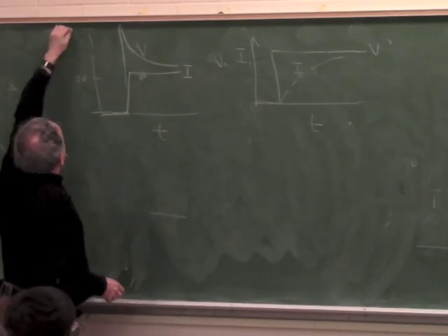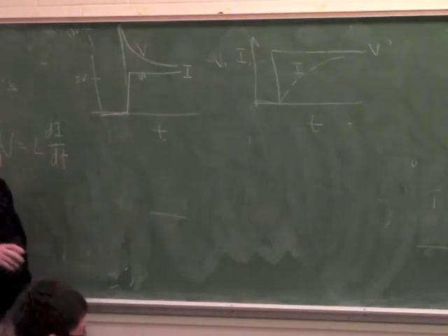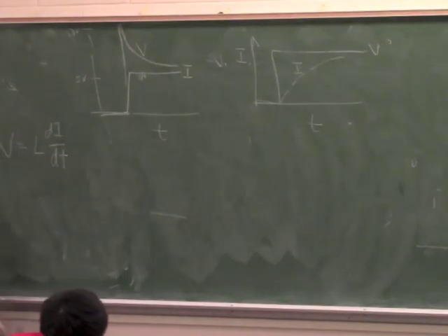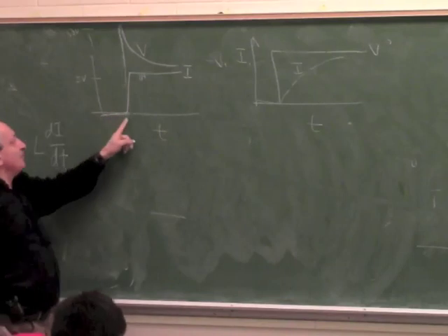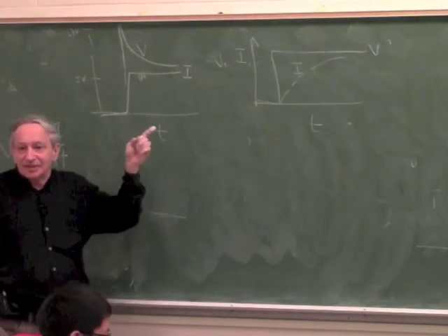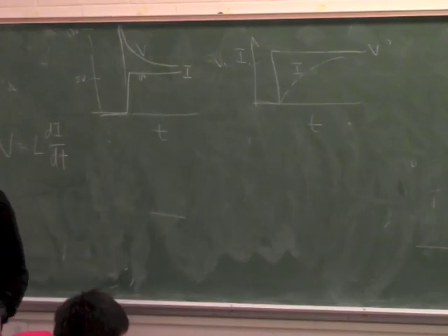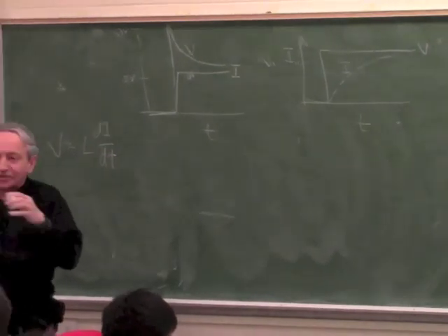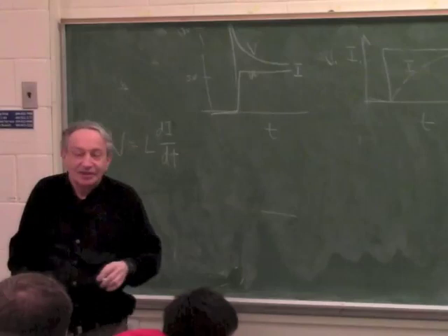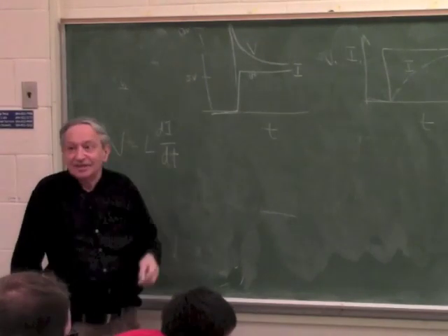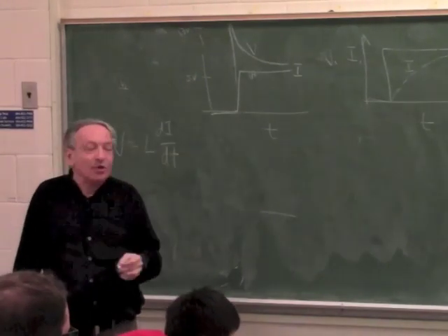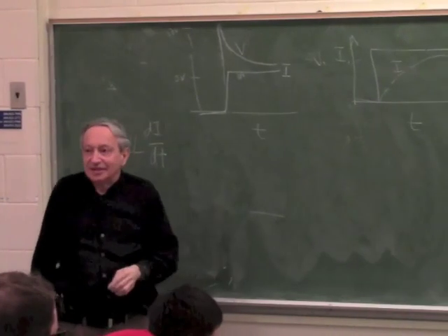You start with a 50 volt drive, so it will be almost like constant current. This will give you a much faster rise time. Is that clear to everybody? So in all your labs, when you have a box called micro stepper driver or stepper driver, that's what these boxes do. They try to drive at constant current to overcome the inductance.